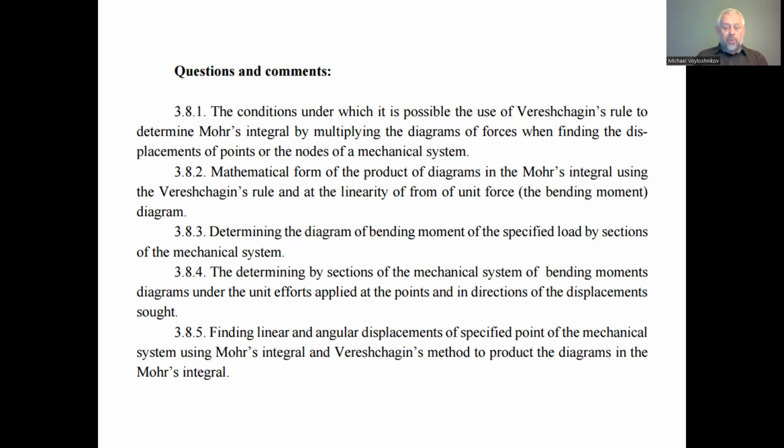The Mohr integral, the integral of the product of two bending moment diagrams, equals the product of the area of one of the diagrams by the magnitude of the bending moment of the other diagram, in projection corresponding to the location of the center of area of the first diagram.